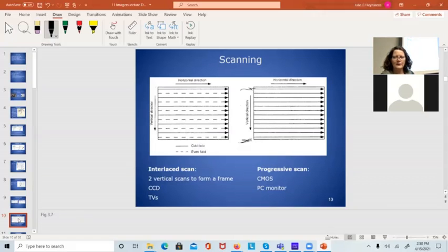And if a guy's running across the screen and you're getting an image of the top of the screen first and then the bottom of the screen later, he's going to be skewed this way. His legs aren't going to be attached to his body. Something that's moving rapidly across the array. And that's probably what's going on in the picture of the boy: you had the camera on its side, and as you're scanning across, you caught the boy's image at a different moment in time than the boy's image in the mirror. Even though it's just a few milliseconds. Yeah, a few milliseconds later.